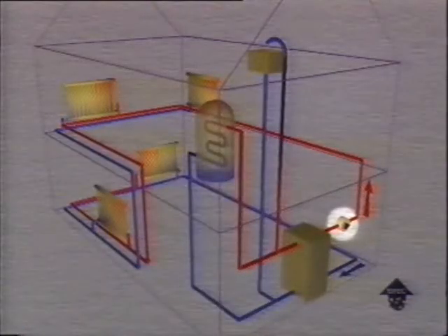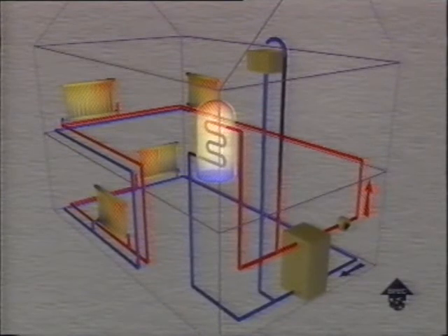But hot water's circulated around the radiators by using a pump. The cylinder has to be high enough above the boiler to be effective. This sort of system is inefficient and costly because domestic hot water's heated to the central heating system temperature, about 82 degrees Celsius, instead of to the more usual 60 degrees.